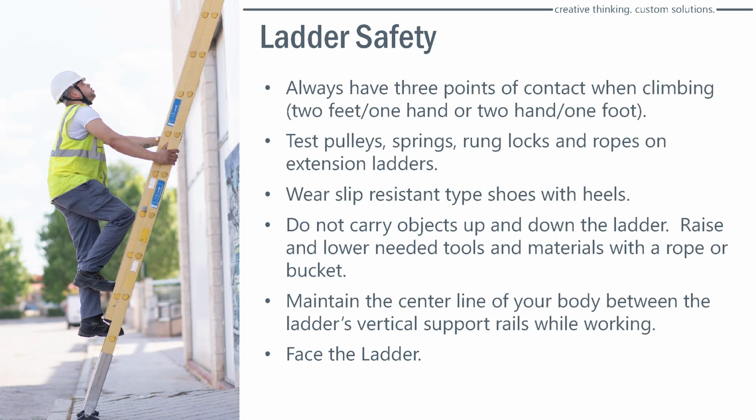Now, this is something I think everybody ought to ensure happens. It doesn't always happen, but it should. Three points of contact when climbing a ladder at all times. Two feet, one hand, or two hands, one foot at all times. What that prevents you from doing is carrying something on your shoulder or carrying tools in one hand, and you can't use that to grasp the ladder. We'll find some other way to take the tools up there, all right?